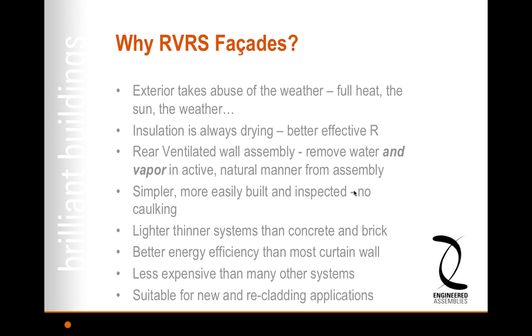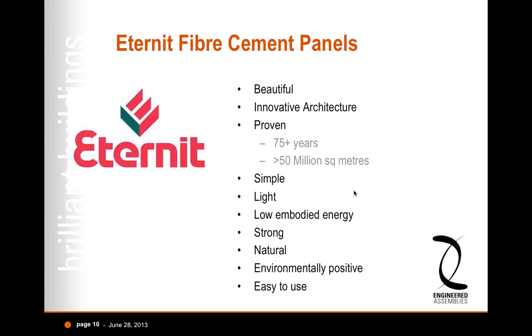This isn't just a drain cavity like in the brick world. This is a truly active plenum. And the fact that this panel has been developed to be so strong, even though it's very thin, is a fantastic value proposition when you think of proper use of materials and preserving our planet. So there's quite a bit to this, I guess, is what I'm getting at about how this meets a ventilated facade.